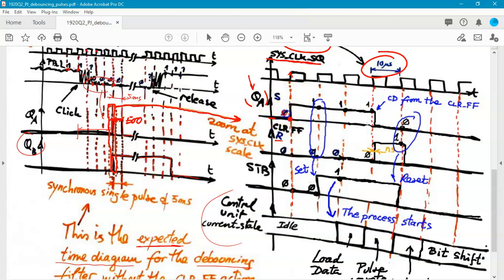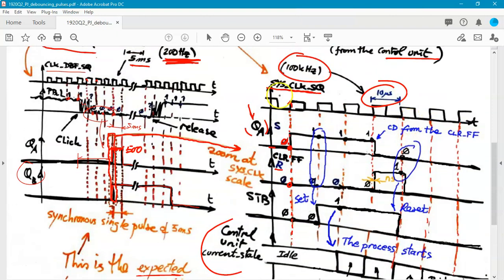So a 0 is detected here. So because the reset that came from the control unit is 0, you have 0, 0. So in a problem like this, it is understood that this is an RS flip-flop. So the Q in the future, if you have 0, 0 sampled, you keep the value, right? So nothing happens.